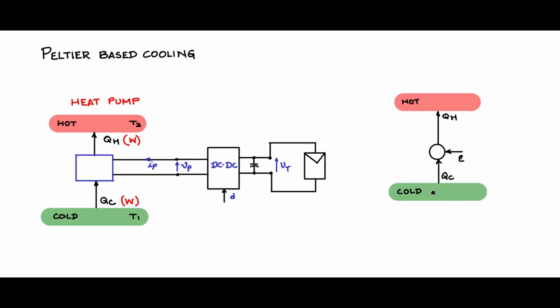When heat has to flow from a cold, low temperature to high temperature, you need a pump. It is much more difficult. But from high temperature to cold temperature, the heat flow is automatic. You don't need the means of a pump. So automatically heat will find a path like this or like this, and then reach the cold junction, and the delta T, what you are trying to achieve, will actually come down, and the temperature difference between these two junctions will not be that much.